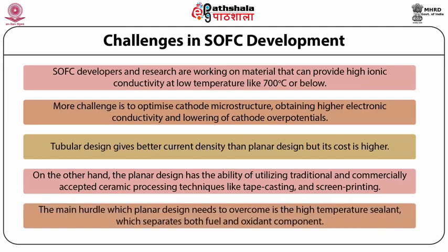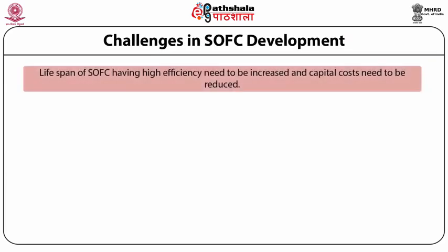The main hurdle which planar design needs to overcome is the higher temperature sealant, which separates both fuel and oxidant components. Lifespan of SOFCs having high efficiency needs to be increased and capital cost needs to be reduced.